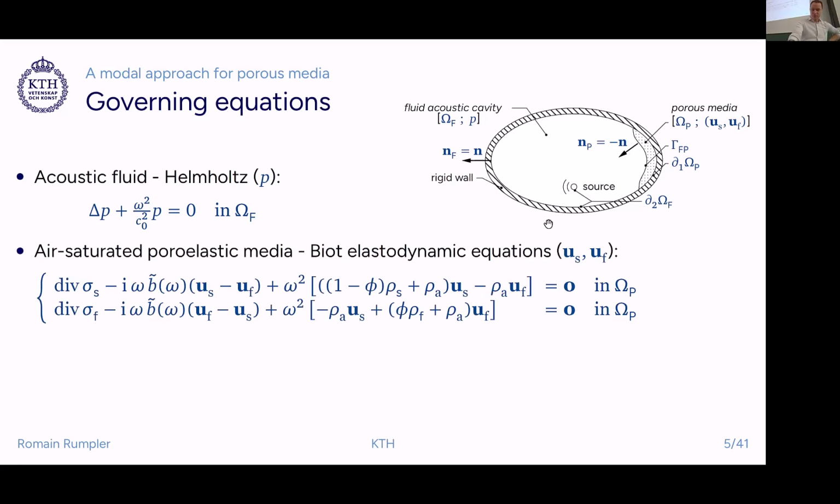So what is the problem then? The governing equations, we have the acoustic fluid governed by the Helmholtz equation, nothing strange here. When we have a look at the poroelastic materials, we will have to deal with the constitutive relations for the solid and the fluid phase. You can see here this viscous term, viscous coupling, difference of displacement between the solid and fluid phase.